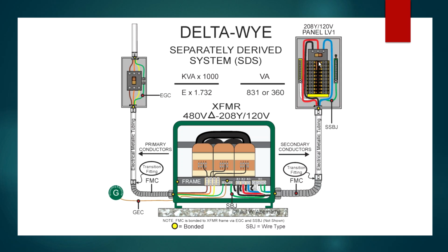So this device in our graphic, whether it's located right here, or we're utilizing the secondary rules or the tap rules, we're protecting this panelboard, whatever our load calculation was. But in this case, a 300 amp overcurrent protection is what we would need to protect the actual secondary.